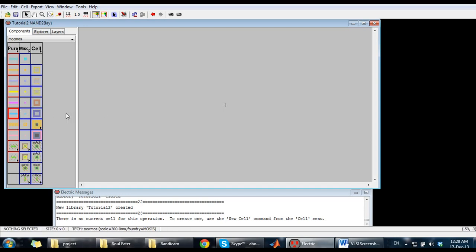The basic starting point is metal 1 and polysilicon 1, so this is why you have a contact for metal 1, which looks like the bluish line here. And this is the gate that we're gonna use to connect our contacts with the transistors themselves.